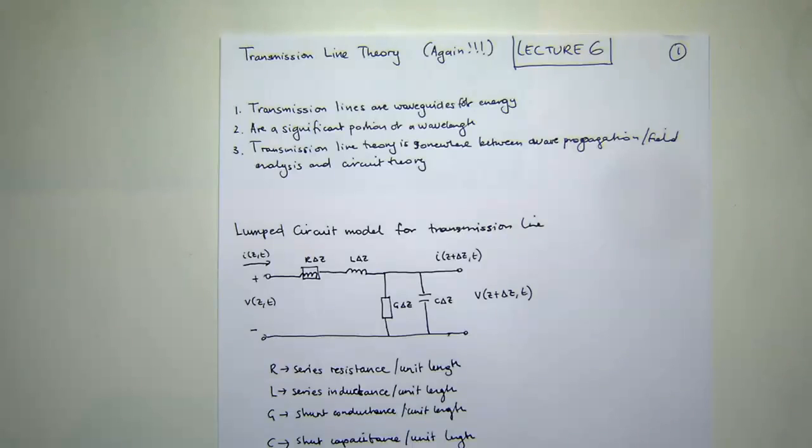Now, what we're doing in transmission lines is essentially the same thing. It's just dressing up Maxwell's equations in a lumped circuit equivalent, right? So we're actually rewriting Maxwell's equations of wave propagation in terms of inductors and capacitors, resistors and conductors. That's all we're doing in transmission lines, right?